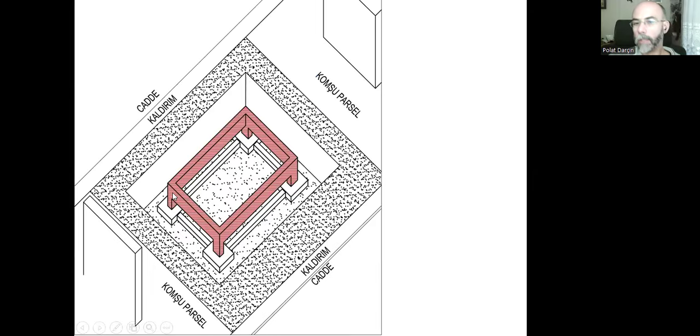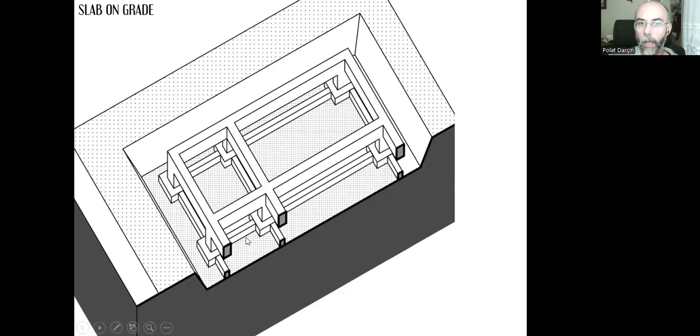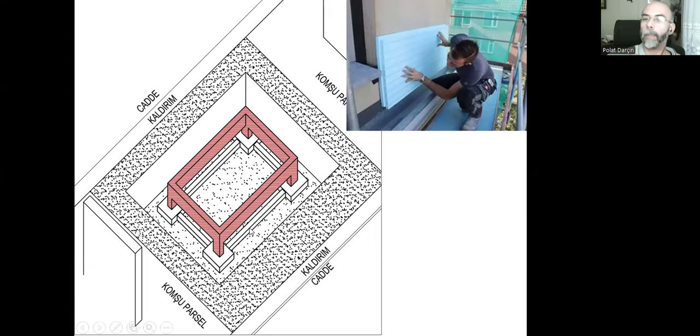That means that once the construction of these reinforced concrete columns and beams is completed, we can cover them with XPS boards easily. You can cut them easily with a stationary knife, and that will be all. As you remember, we created all these reinforced concrete components with waterproofing admixtures, so there's no risk of water damage. We used XPS boards for the heat insulation, and we cover the foundation columns and grade beams with these XPS boards, so we stop the heat transfer.